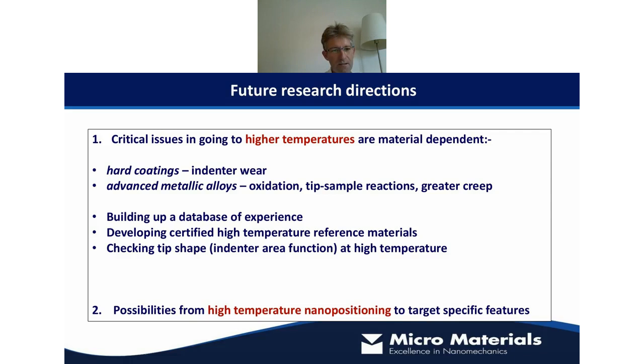One thing I just touched on earlier, but it is very important, is to either check the tip shape at high temperature or immediately after cooling back down. Particularly for testing bulk materials, it is possible to recalibrate for that and still get reliable data. But if you don't, your hardness and elastic modulus will be overestimated.